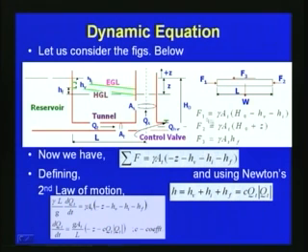Now F1 is obtained as gamma AT into H0 minus HV minus HI, and then F2 on this side, with respect to this figure, we can write as gamma AT into H0 plus Z. And then F3, with respect to the friction loss, we can write as gamma into AT into HF, which is the friction head.